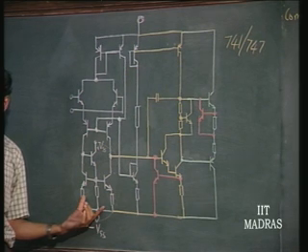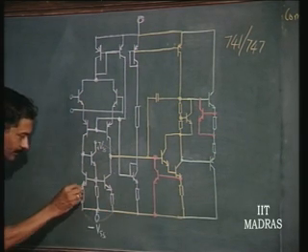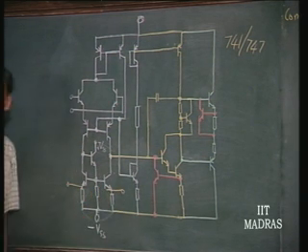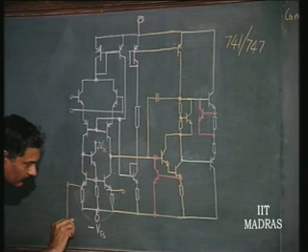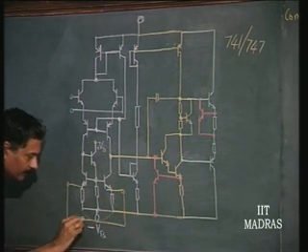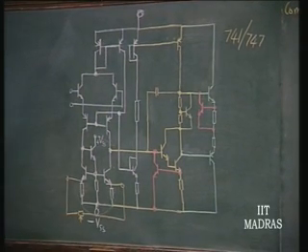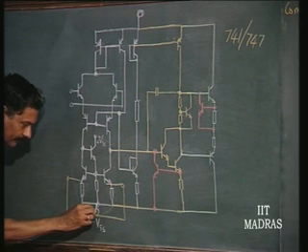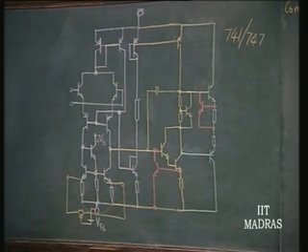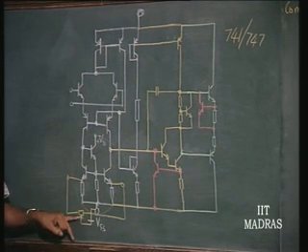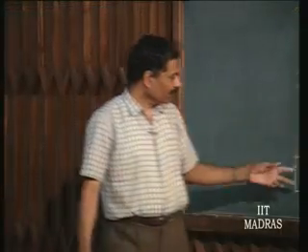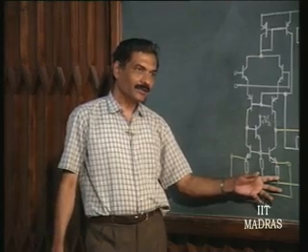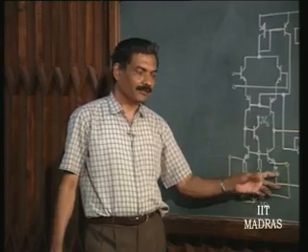That is why this is an easy technique of compensation. Now, how do I do it? The manufacturer puts equal resistors, then he brings out these two terminals and mentions these as offset compensation terminals. One has to put a potential divider between these two, and the center tap one will connect it to minus Vs. So, what happens if it is center tap, then equal resistances will be across this. If the tap is deviating from the center position, then we will be generating unequal resistance. Depending upon the kind of offset, you can either increase this resistance related to this or decrease it related to this just by using a pot here.